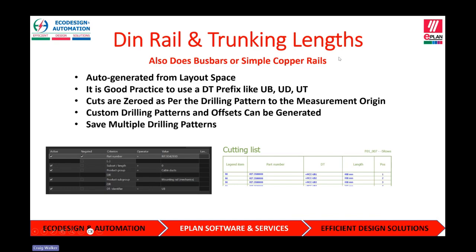The DIN rail and trunking lengths, again, come directly from the layout space. Once you've placed your DIN and ducting, as long as I usually use a DT device tag prefix, like UB for bus bars, UD for DIN rail, and UT for trunking, I can filter based on that for a parts list, which I call a cutting list.